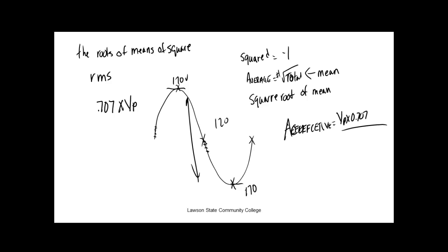Now, when we start dealing with DC power supplies, we're going to be dealing with peak, so we need to know peak. But then, of course, we need to know what our meters read. Standard meters read RMS. If I had a true RMS meter and put it on that outlet right there, and I took this meter and put it on the outlet, it'd measure exactly the same thing. So my $200 meter and my $100 meter measure exactly the same thing because it's looking at a sine wave. If I had a variable frequency drive or variable speed drive on an AC motor, and I looked at it with this meter and I looked at it with a true RMS meter, they would measure something different.